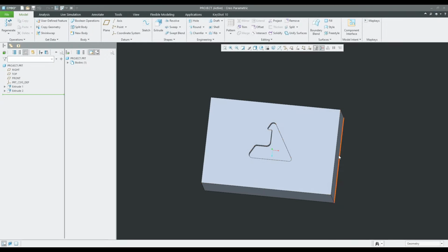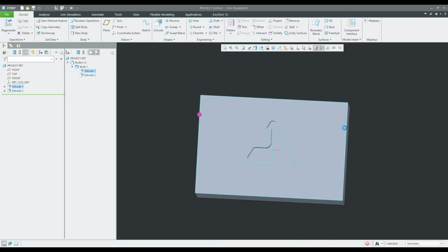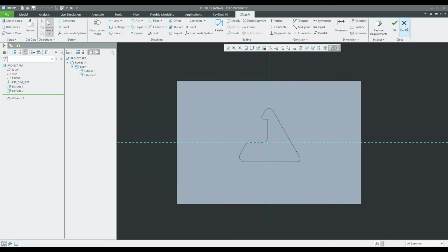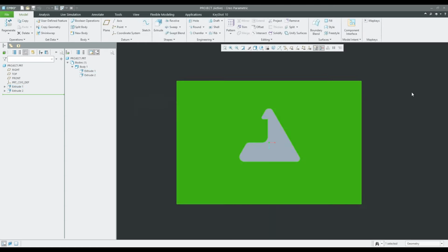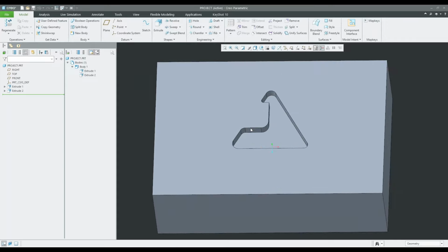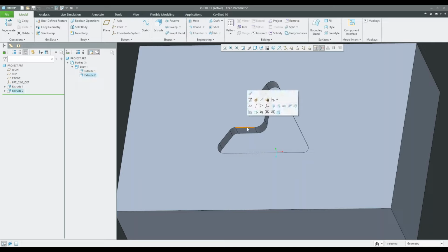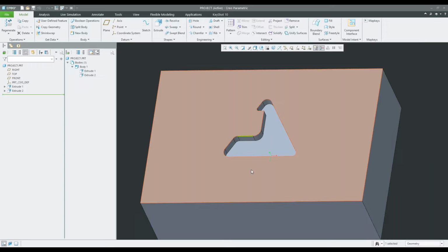Okay. So let's go into our Sketcher environment. All right. So just like, and I'm gonna get out of here first. So previously, when selecting an entity or an edge on a model, like this cut, for example, if I grab this top edge, right, I can hold Shift, I can get my chain, I can right click until I get the selection that I want, or I can hover over the top surface to get the whole edge loop, right? So we are used to using those selection techniques outside of Sketcher.